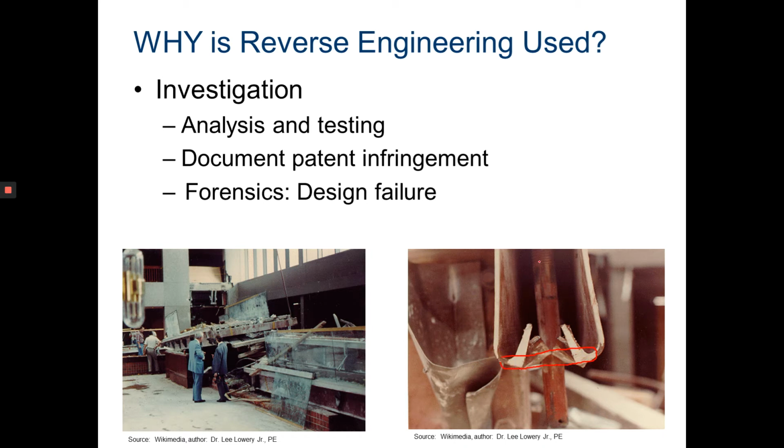So what happened is, if you look up here, you can see threaded rod. And so basically what they did was they attached some nuts to the threaded rod and expected that this welded box beam was going to hold. Sadly, it did not. And what happened is the nut basically pushed through the metal, and that allowed the system to collapse down on itself.